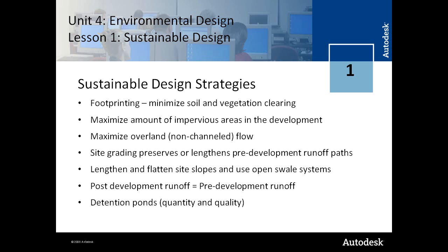For example, in a hot area, you may store water on building roofs, and it might get hot from running off of paved surfaces and parking lots, and to discharge hot water into a stream could be harmful to the natural habitat of that stream. So sometimes detention ponds are used to actually cool water before it's allowed to discharge into the existing natural water network at a controlled rate.